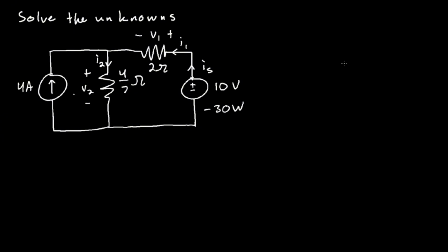Alright, so first thing I notice, boom, we have the watts at this voltage source with the power absorbed. So using the power calculation, you can solve for the current I of S. But remember that this current is going into the negative side first. So I of S, we can of course move I of S down into here as well if we wanted to. But since this current is going into the negative side of your source first, that means that you are using the not passive sign convention formula. Therefore, power is equal to negative voltage times current.